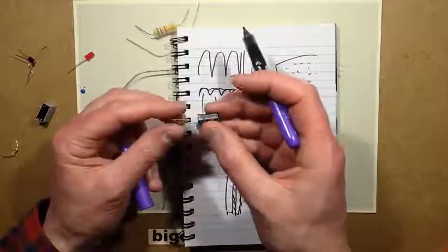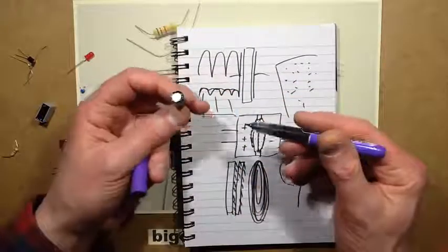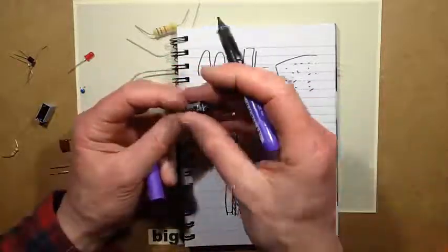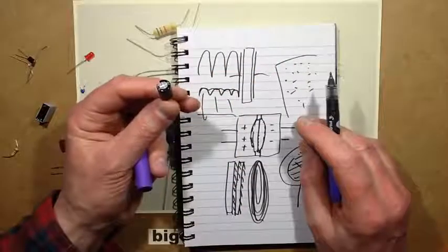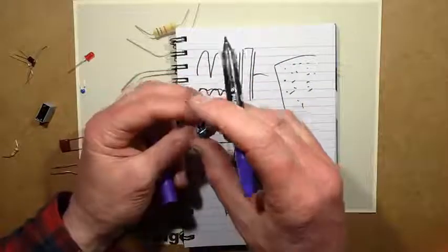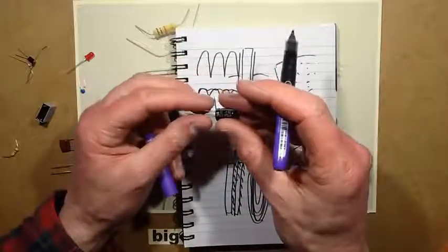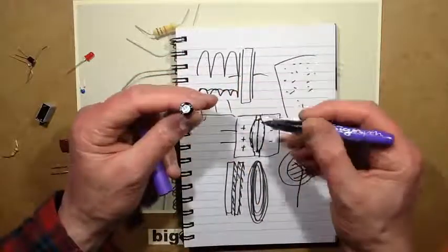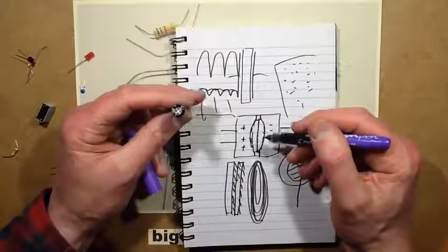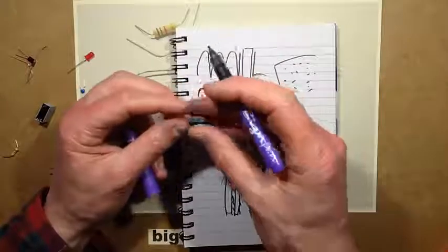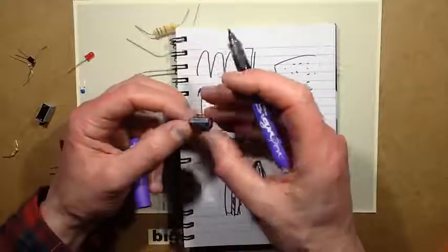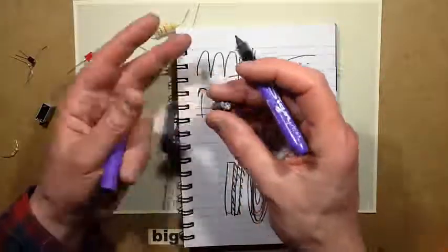However, that's more of an issue with modern electronics, because whereas in the old days these capacitors only had to deal with like 100 Hz or 120 Hz, just mains frequency rectified, nowadays the capacitors have to deal with the output from switch mode power supplies, which is like thousands of hertz, tens of thousands of hertz, and it means that they actually heat up and they dissipate more energy.